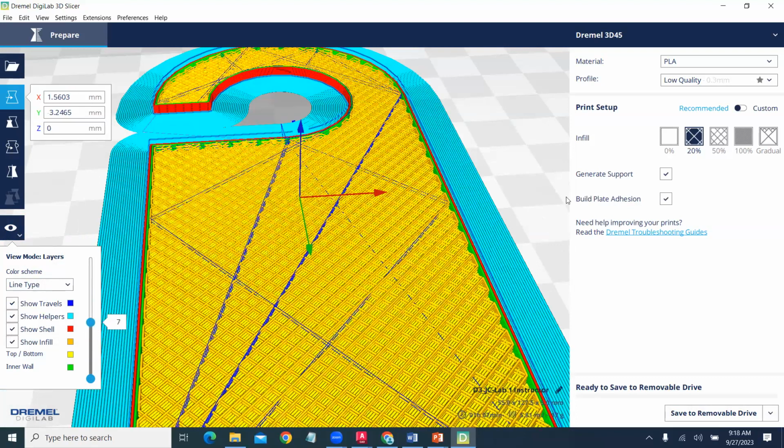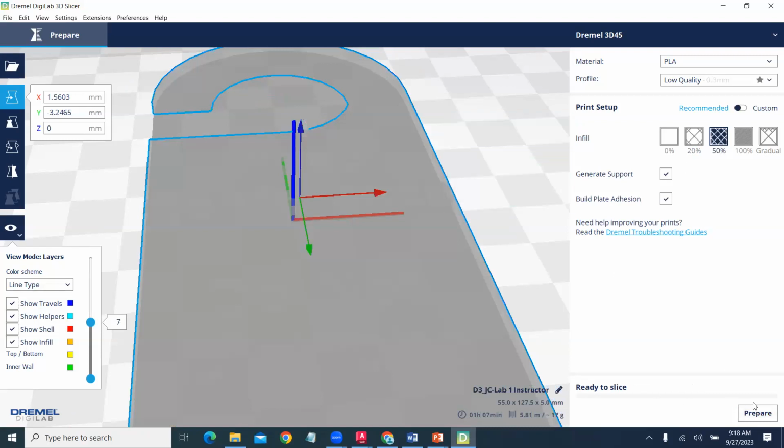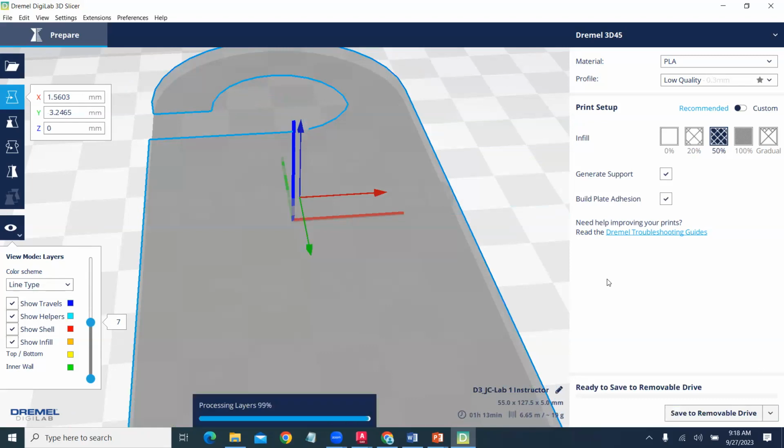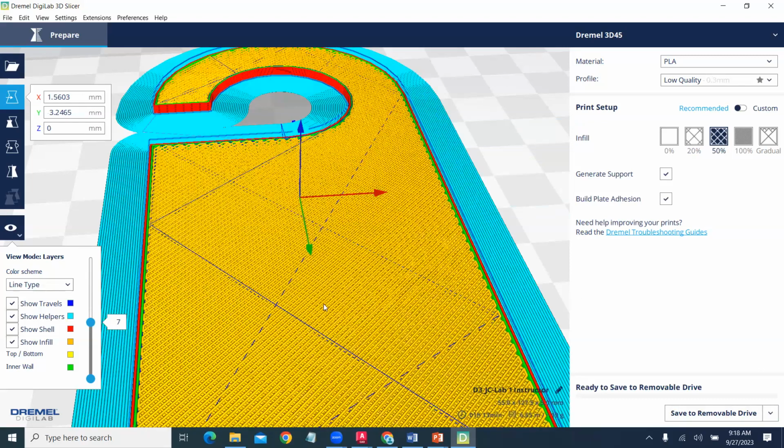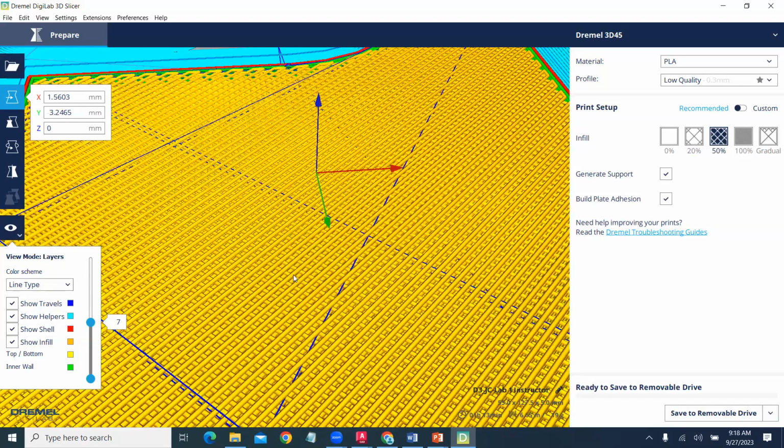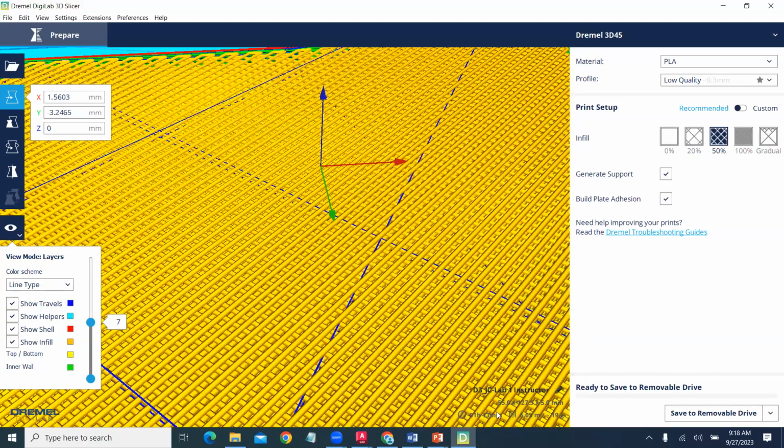And this is our infill pattern at 20%. And so the more infill, the stronger the part. But the more infill that we have, the longer it takes to build. And so if we increase the infill percentage, we have to re-prepare it. And then we have now a higher infill amount. And then the cycle time will typically increase.